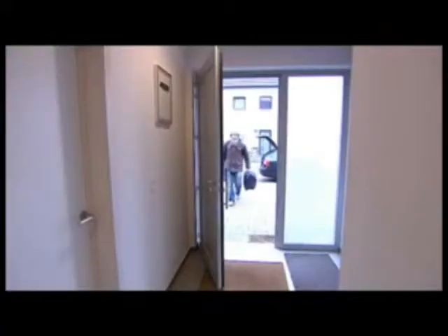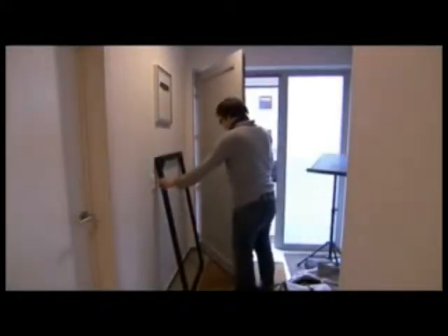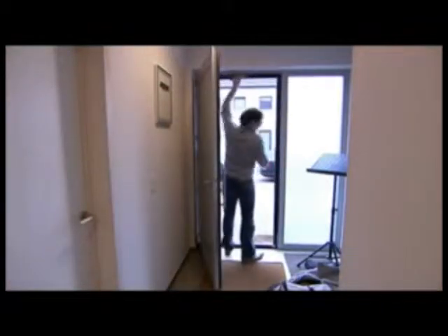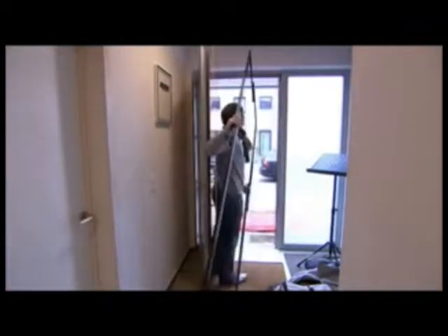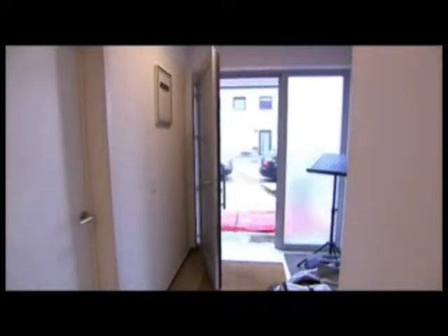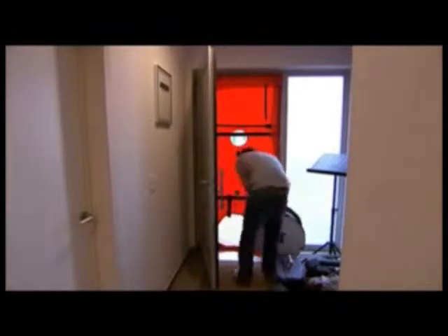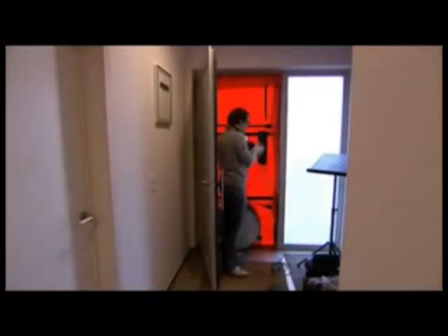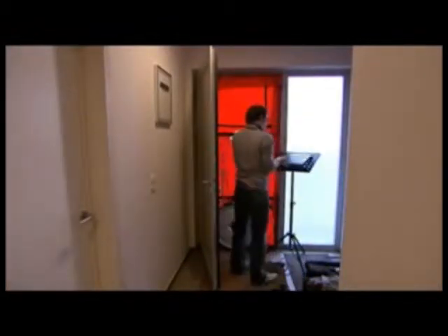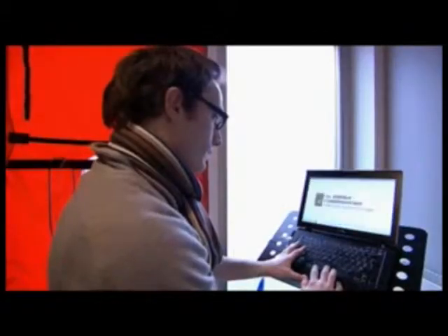Thermal imaging can also be used inside buildings. Air leaks in buildings can be visualized by identifying the air change rate with the help of what's known as the blower door process. This process creates underpressure in the building. Since the air pressure outside the building is higher than the pressure inside, air will try to enter through unsealed areas. Air leaks can easily be visualized with a thermal imaging camera.